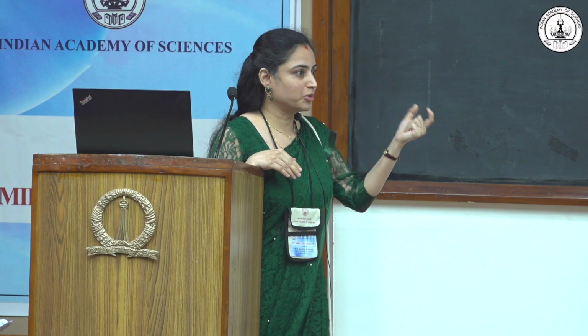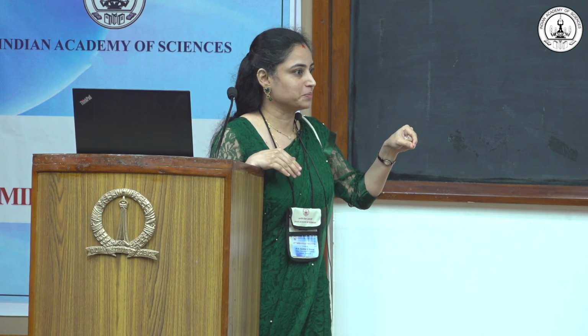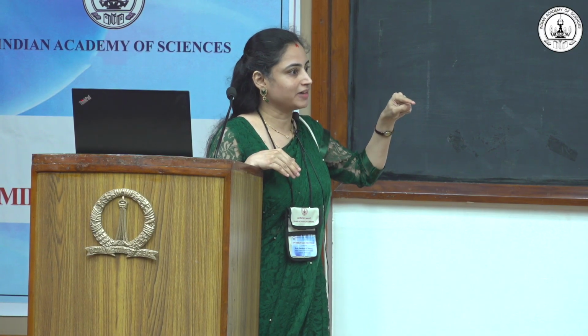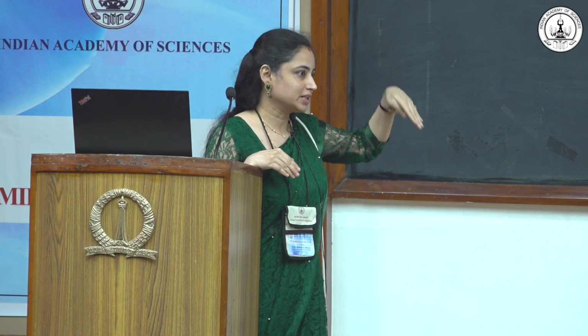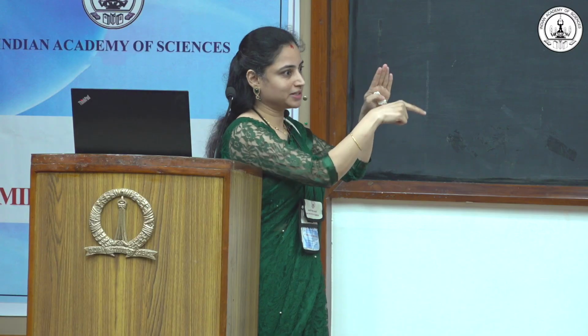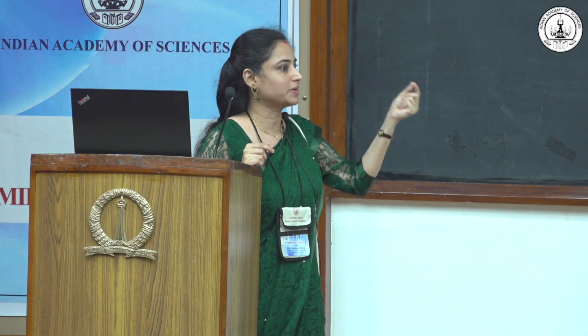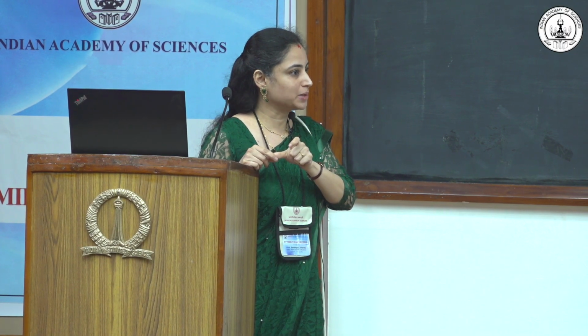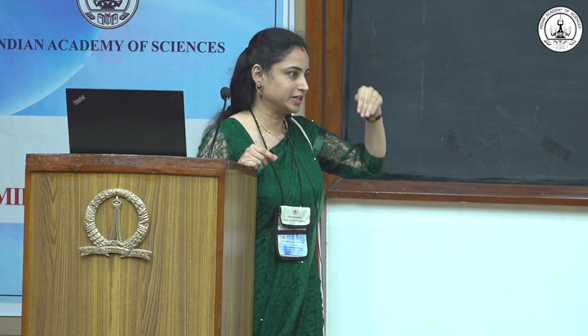So, you have done the finite temperature calculation? No sir, that is a well known thing, the amount of band gap required for a particular temperature is already established. What we do is we just check the conductivity values, the Seebeck as well as thermal conductivity values. If at all there is bipolar diffusion, there will be an upturn in thermal conductivity, or in case of Seebeck there will be a downturn. Based on that we will know whether there is bipolar diffusion occurring or not. Okay, so you use the Fermi-Dirac distribution for the calculation? We don't actually calculate the amount of bipolar diffusion, we just check if the Seebeck coefficient is increasing or decreasing.